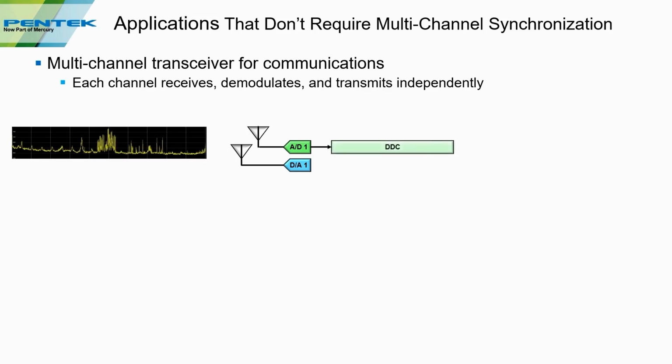That'll go to possibly a digital down converter or a DDC. The reason for that is that it allows you to take the entire spectrum and tune it in to a specific band that you're interested in. Now in this system, in addition to demodulation, there may be decryption, there may be a secure band that people are communicating on, but ultimately that'll get decoded and it can go out to a human operator.